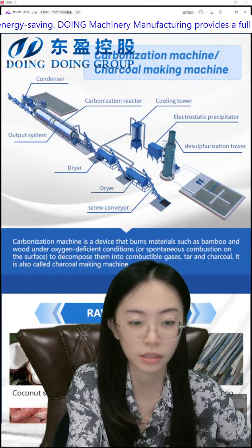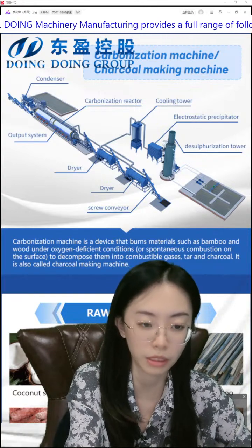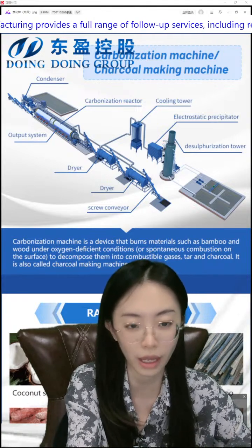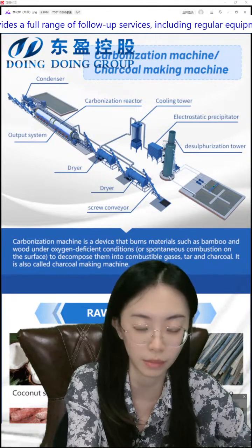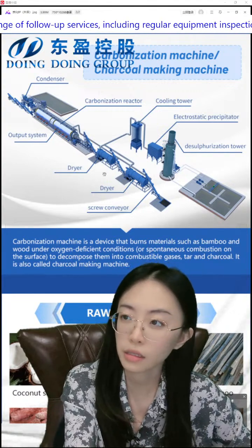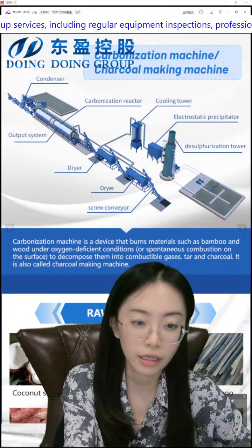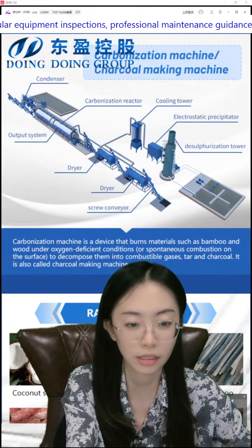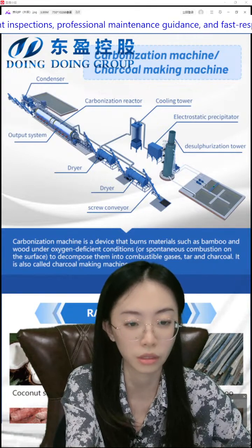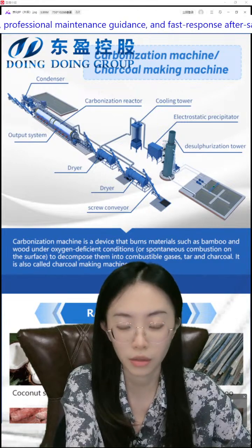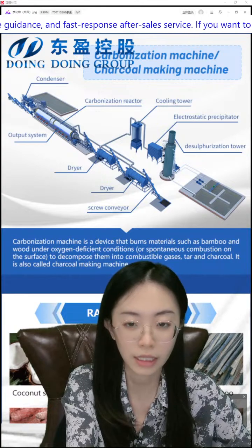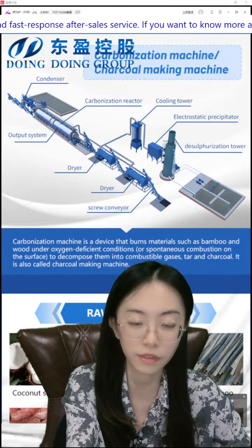So this is the design to break up the raw materials and have even contact with the hot wind, and just lower the moisture. The dryer is inclined, so we can transport the raw materials forward. The angle of the incline is 30 degrees to 50 degrees.